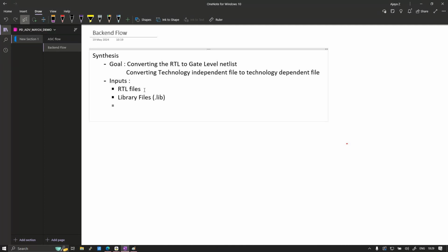Okay. So next, if you have power intent information, you will be providing the UPF file also. Power intent information, to be brief, is multi voltage design or power switching related information, which will be present inside this UPF file. And the voltage level of that particular design will also be present inside this UPF file.